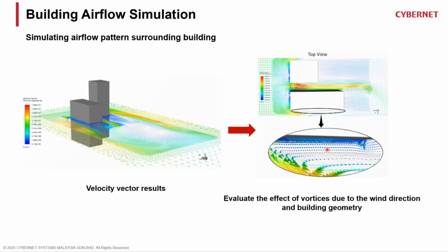So in this example, you can see that the air is moving here, but here there's more of a vortex, because of the shape. Once it hits this edge of the building, it just recirculates, sort of creating a vortex shape. So what it's saying here is that you actually have a very empty, low velocity flow area around this edge, this side of the building. So again, you can see this kind of effect through the simulation results.